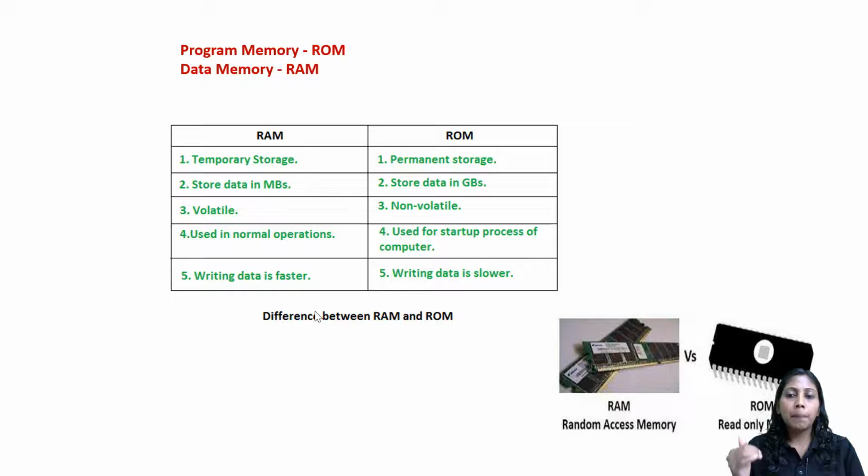Read only memory is the permanent storage; keep this in mind. Once I write the program on the host machine, compile it, and create the hex code, I use a cross compiler to dump the code into the microcontroller ROM. Once it's done, it's permanent storage and nobody can alter it. But if you want, you can reprogram the device, no problem. It's not that I can program the controller only once. If you have some errors or want to add some features, you can reprogram it.